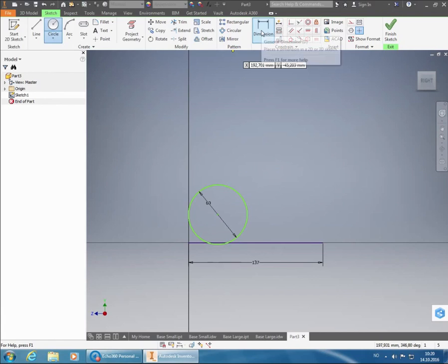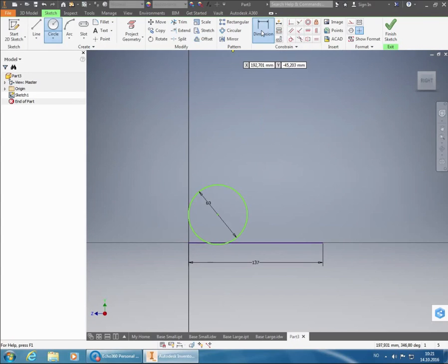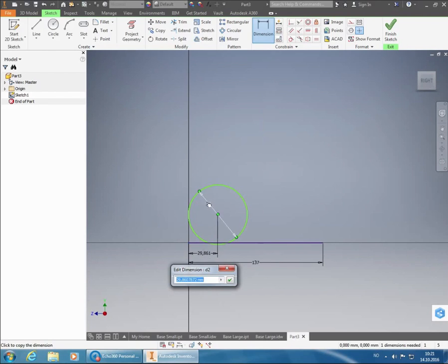And we're going to use the same as last. We're going to set the horizontal length between the end of our baseline and the center of our circle as the radius of the circle, just to lock it into place. And in order to get some automation into it, we click on the diameter, selecting that dimension, D1 in this case, and we divide by 2.